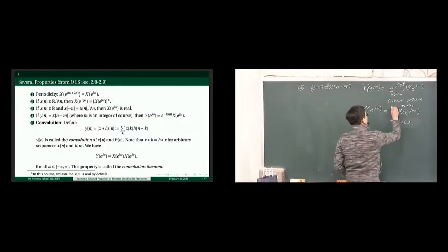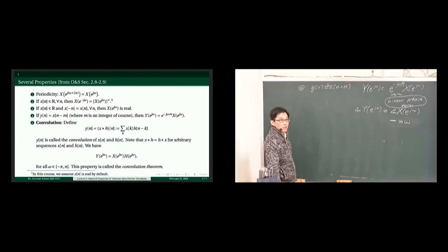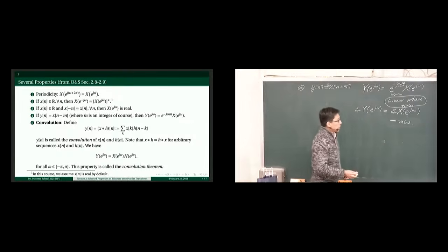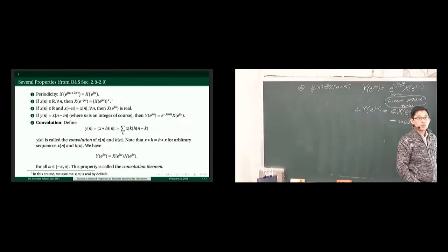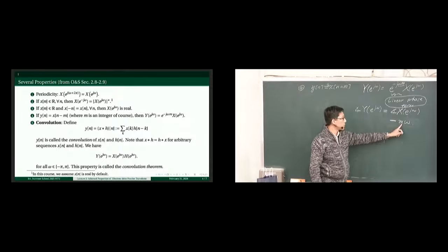That's a very important and basic concept which is mathematically true and not hard to interpret. I'm pretty sure that by some contemplation you can create your own way to understand this property. When we introduce a delay in the time domain, that leads to a phase delay in the frequency domain for every frequency. The phase shift is different for each frequency, and it's a linear phase shift, proportional to the frequency, m being the time.